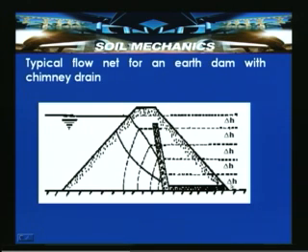In this case, for these lines 1, 2, 3, 4, 5, equipotential drops have been considered. So, ND will be equal to 5, and NF is approximated as say 2.5 or so. In that case we can approximate the ratio NF by ND, and by knowing the material K and by knowing the H which is there, we can again estimate the quantity of the seepage.